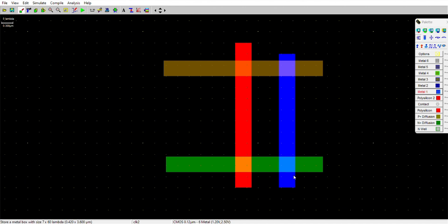After making the NMOS and PMOS, you connect them through a series connection using metal 1 from the palette layers. A bit of metal to connect to ground and a bit of metal to connect to VCC.